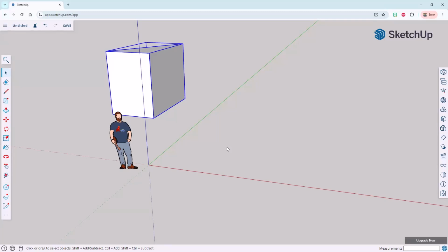Okay, so that was generating a free form. We weren't really focused on the exactness of it, but now we are going to do that. So let's move on to the next practice here. I'm going to click on this icon, which draws or helps me to draw a rectangle. So I'm going to click on rectangle, and R is the keyboard shortcut. So I click on rectangle.